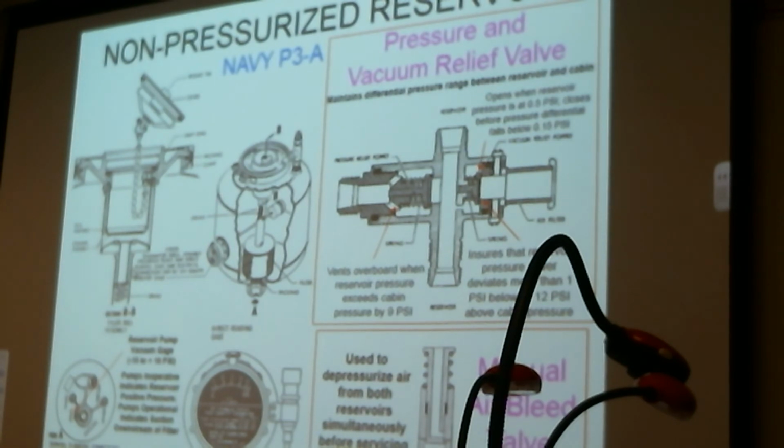Oh, something kind of strange. With fluids, generally, when you apply heat energy to them, with most fluids, do they expand or do they contract? They expand. Well, on one particular aircraft, in this case the P3 aircraft, they allowed the theory of fluid expansion to provide for reservoir pressurization. As the fluid becomes hot in operation of hydraulic components, it allows the fluid inside of the reservoir to expand. What that does is it decreases the volume of space above the fluid in the reservoir and provides for the push of fluid on that fluid.